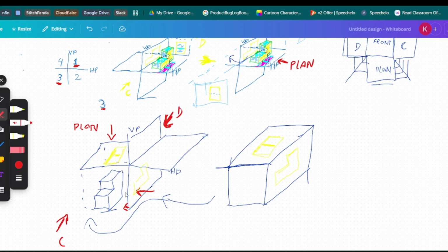So in third angle projection, if we're looking at this, we could use this plane here, this angle here, as an actual mirror, meaning all of the details will rightfully be on this projection. Solid line. Because the face that C will have is here and here. So we transfer that and this line will be solid because the detail is facing C. C is mirroring that exact same image there.